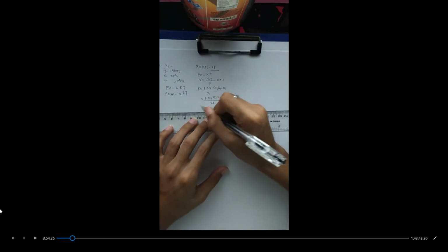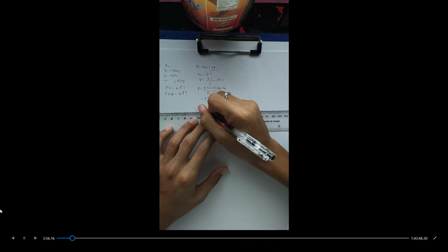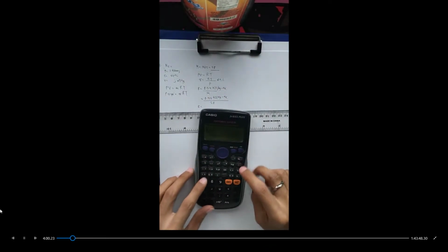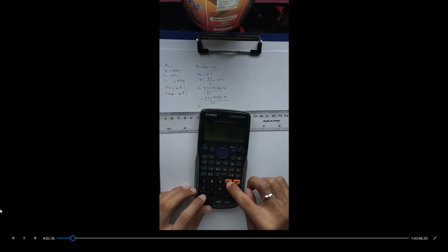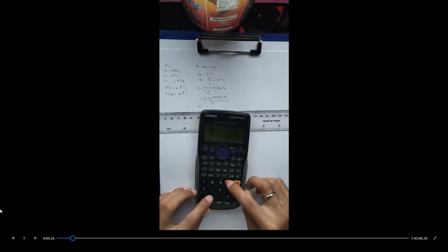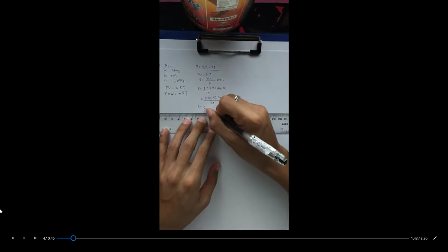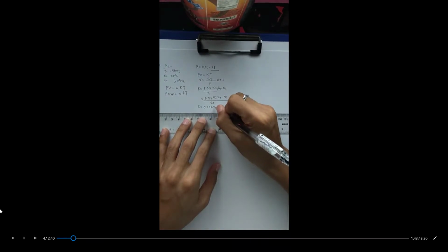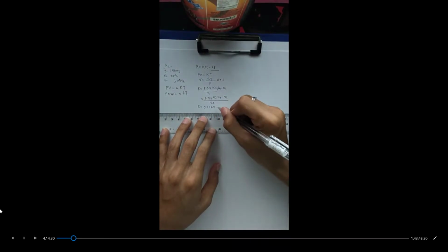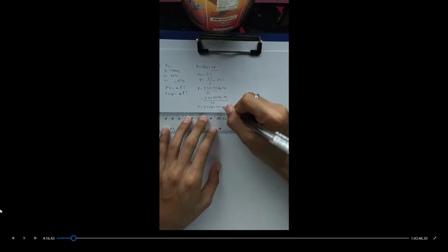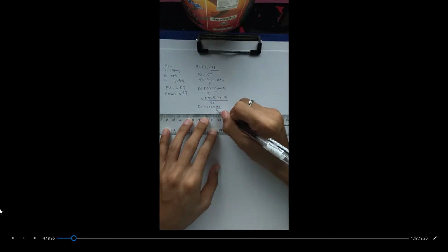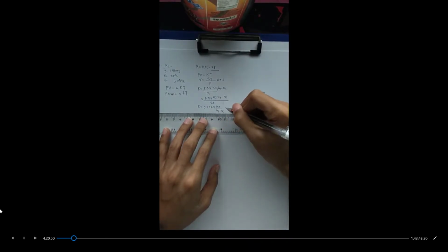So by solving for our gas constant, simplifying our constants, 8.314 divided by 28, our gas constant for nitrogen is 0.2969 kilojoules per kilogram degree Kelvin.